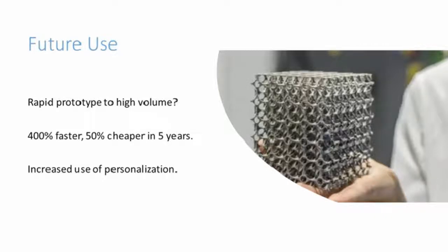Having researched this area in order to deliver this webinar, I personally see no compelling reason to switch from conventional manufacturing to ALM in the short or medium term for high volume and low variety production lines. ALM's greatest utility is its ability to produce complex shapes accurately and without the requirement for moulds. I believe that this switch to high volume ALM manufacturing will only occur when the advantages of additive manufacturing techniques in terms of material usage provide a significant cost benefit when compared to conventional reductive methods. Instead, I believe we'll see greater use of ALM in customized, low volume or high complexity applications.